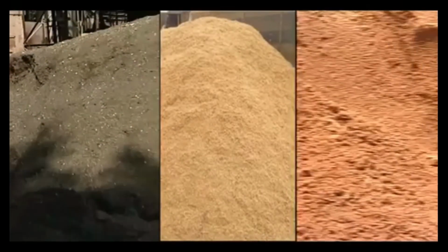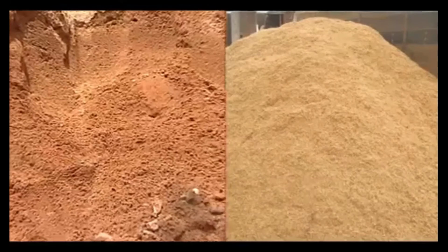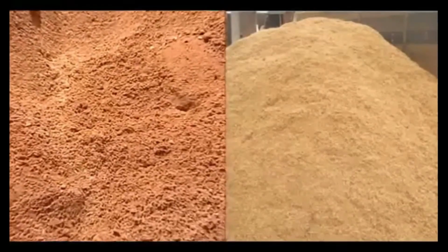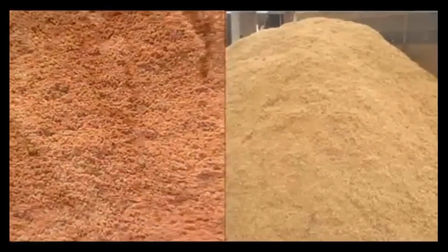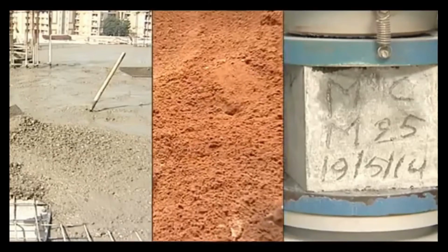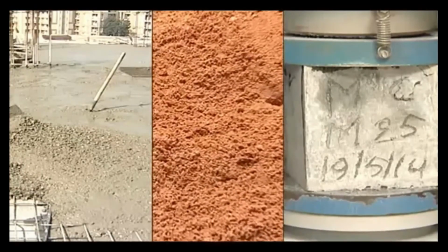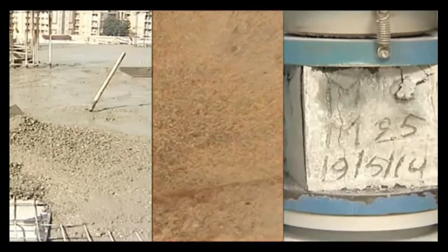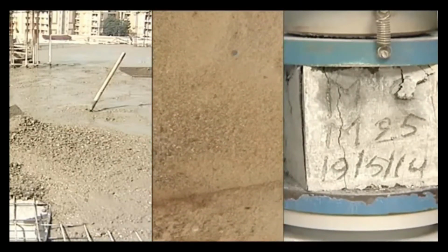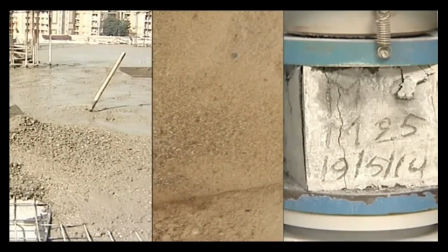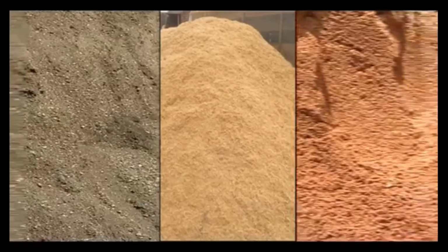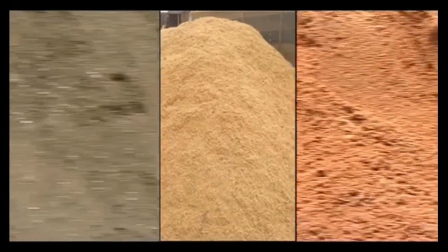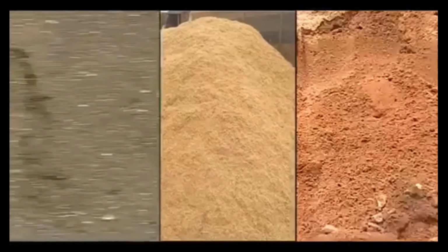Preparing fine aggregates. The sand that is used in concrete is called fine aggregate. Just as with coarse aggregate, fine aggregate has different sizes. It is graded to get the different sizes used in concrete. Generally, both the coarse aggregate and the fine aggregate are washed before being graded. Washing removes particles that are too small. Rock dust or clay often found in stone or sand would be examples of such particles. The prepared aggregate is stockpiled until it is needed.